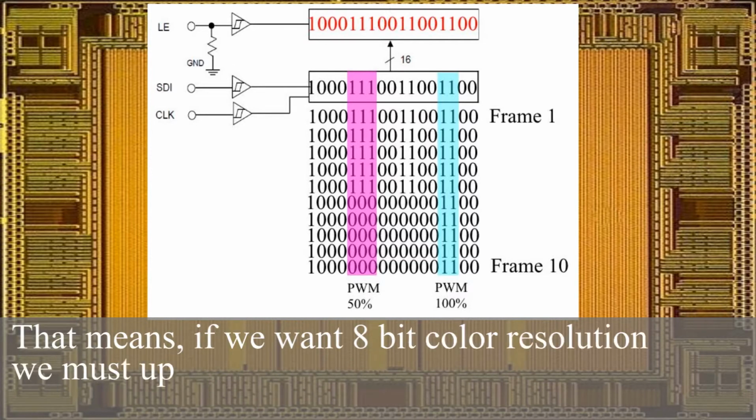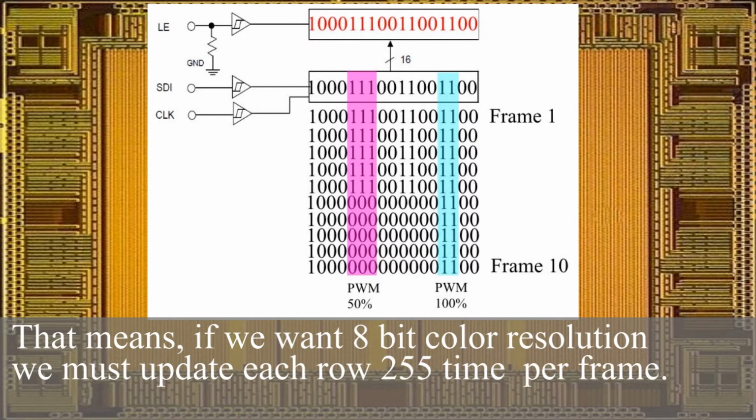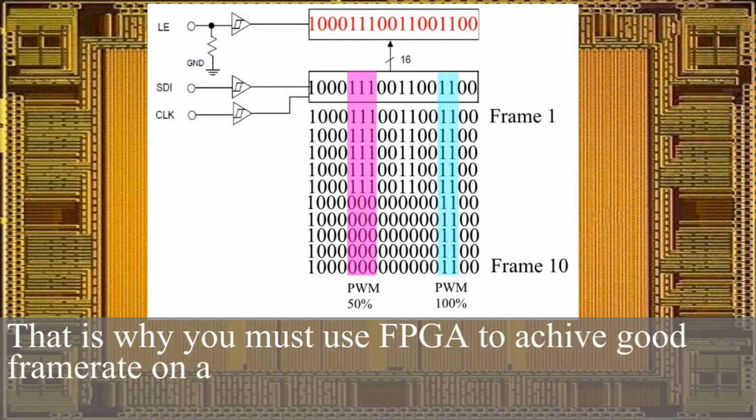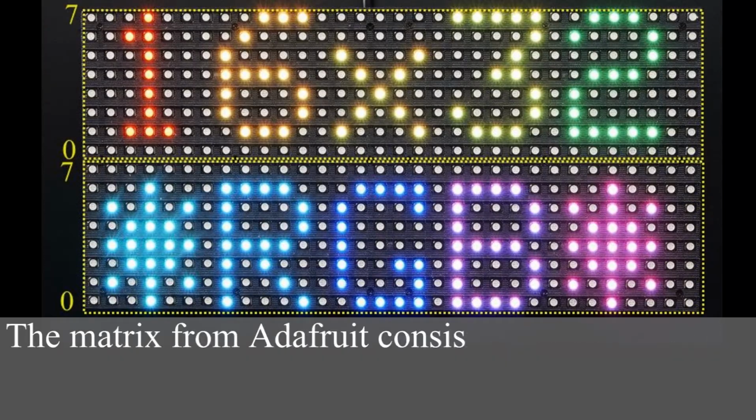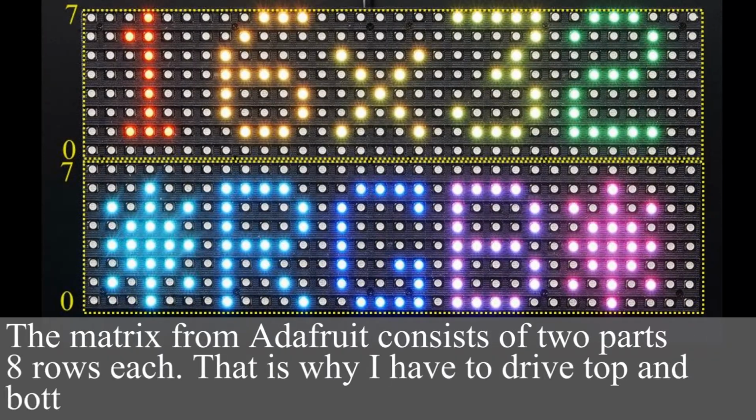That means, if we want 8-bit color resolution, we must update each row 255 times per frame. That is why you must use an FPGA to achieve good frame rates on a big LED matrix. The matrix from Adafruit consists of two parts, 8 rows each. That is why I have to drive the top and bottom half simultaneously.